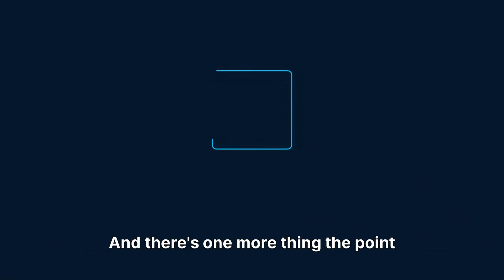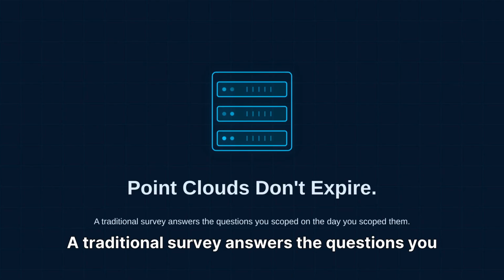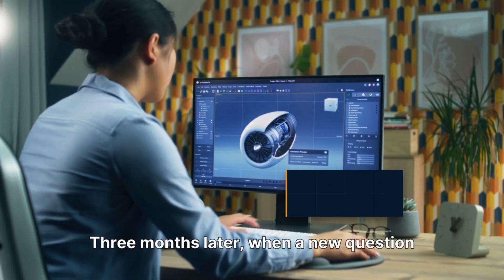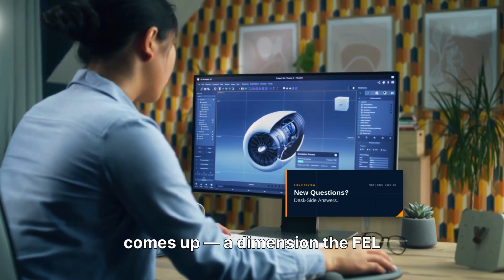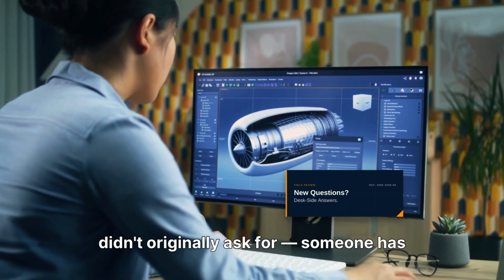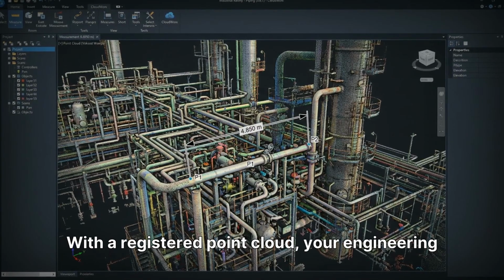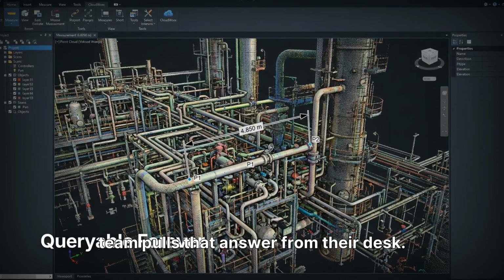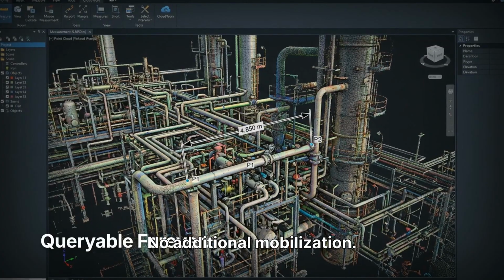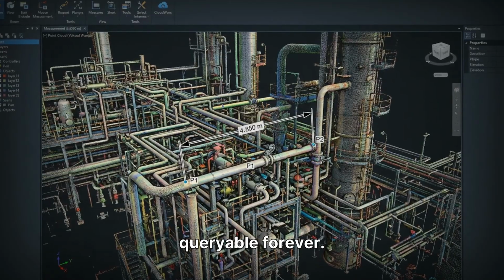And there's one more thing the point cloud gives you that a survey doesn't. It doesn't expire. A traditional survey answers the questions you scoped on the day you scoped them. 3 months later, when a new question comes up, a dimension the FEL team needs, an elevation the piping designer didn't originally ask for, someone has to go back to the field. With a registered point cloud, your engineering team pulls that answer from their desk. No return site visit, no schedule hit, no additional mobilization. The information is already there, captured once, queryable forever.